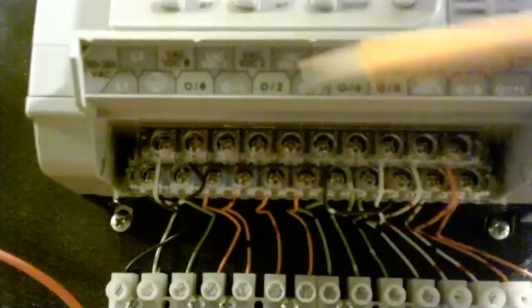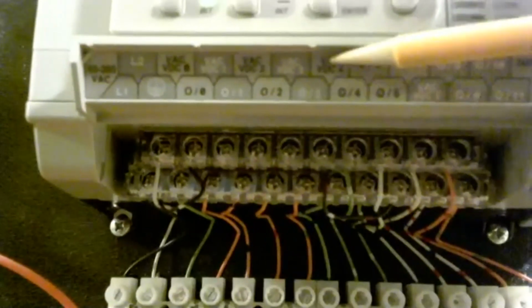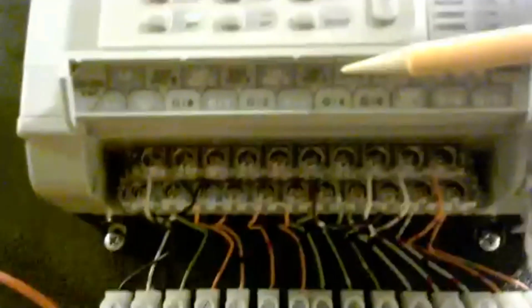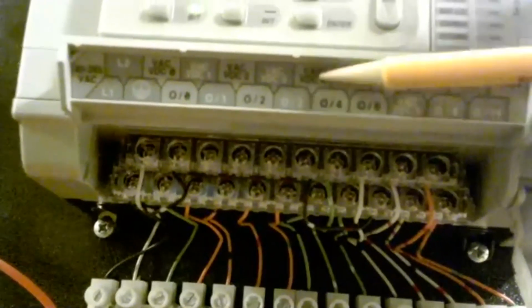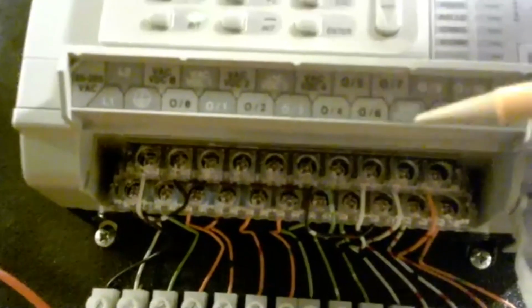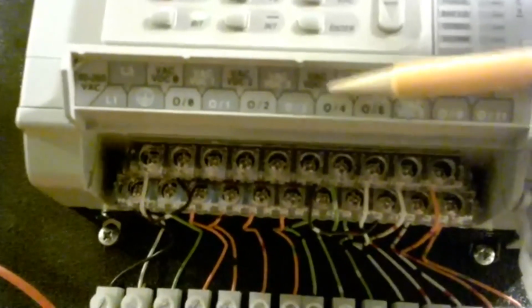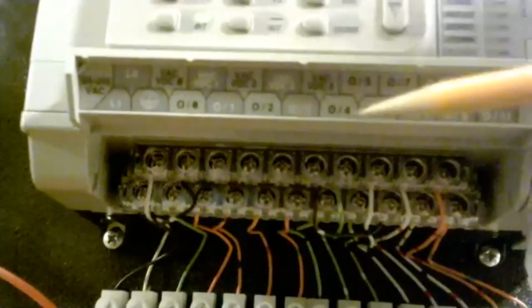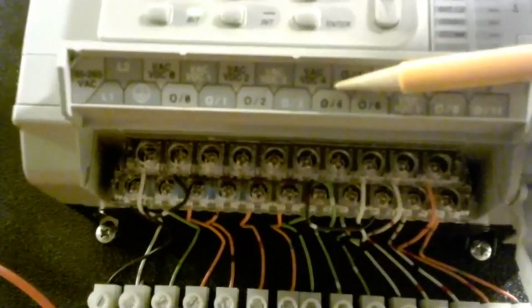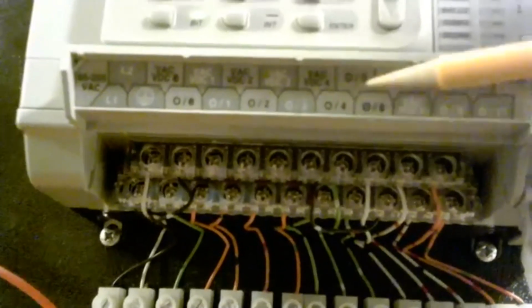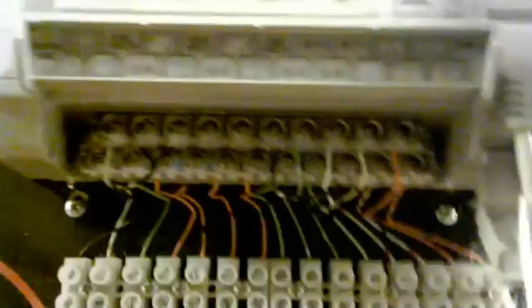And once you get beyond that, then look at here. VAC 4. Can you read that? Yeah. The VAC 4, get this now, it supplies power for a whole group. So that one hot terminal, you see how the shade of this is a lighter color. So VAC 4 supplies power for output 4, 5, 6, and 7.